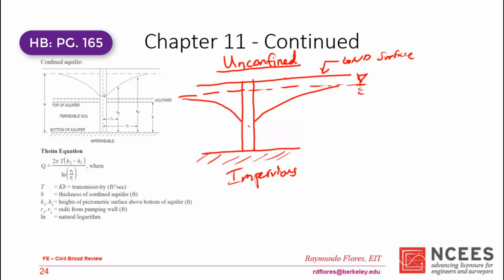Basically this steel pipe that you puncture into the ground can only influence the disruption of the water table to make it curve this way in a certain area. So it's not going to be like this all throughout. You would expect that eventually it would level off the way it should always be. And it converges that way.